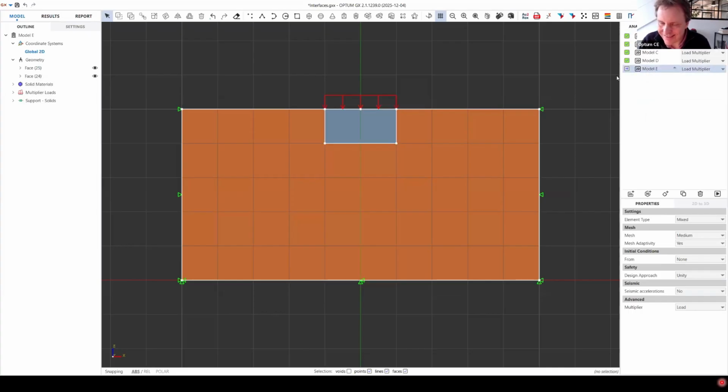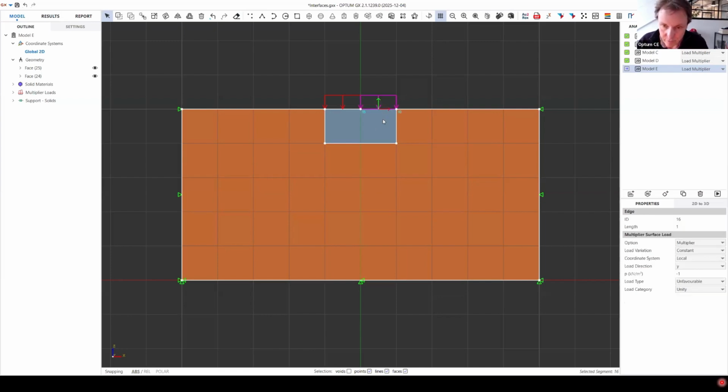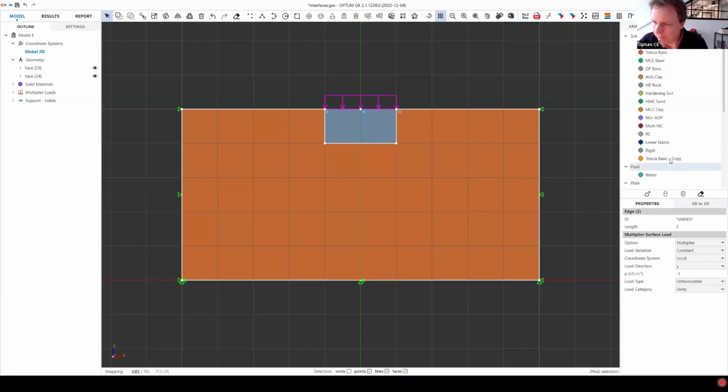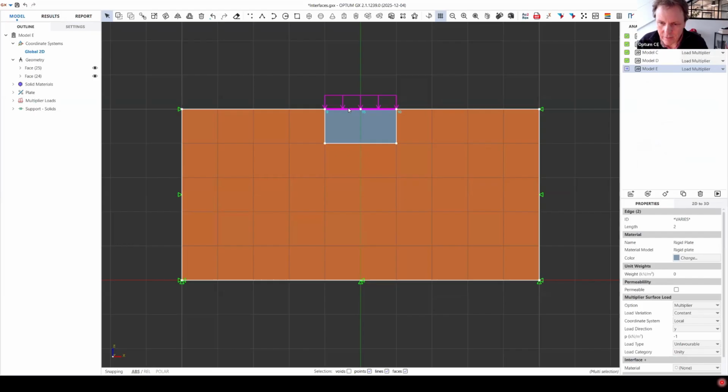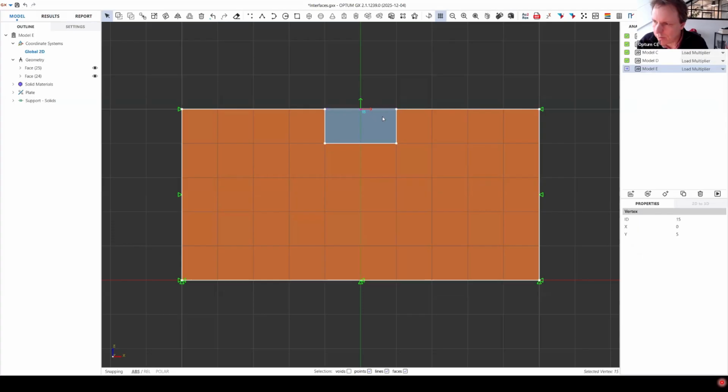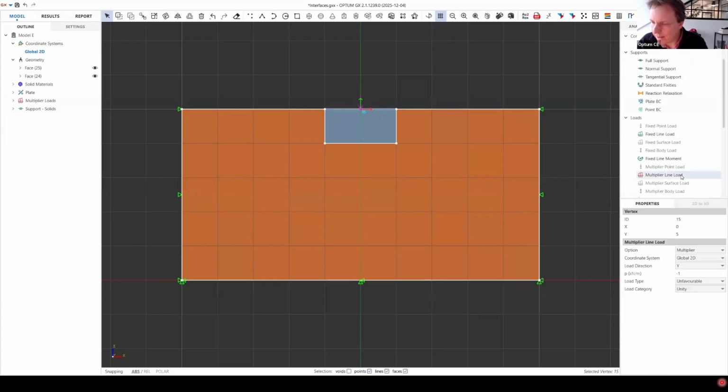So if you work with solids, the surface load here is the only real load you have at your disposal, which is not always very convenient, especially if you have some moment loading as well. So for that reason, it might be a good idea, if you really want to have the solid, to simply apply a rigid plate on top of the rigid solid, and then to this corner, to this central node, you can apply line loads, kilonewton per meter line loads extending into the plane.